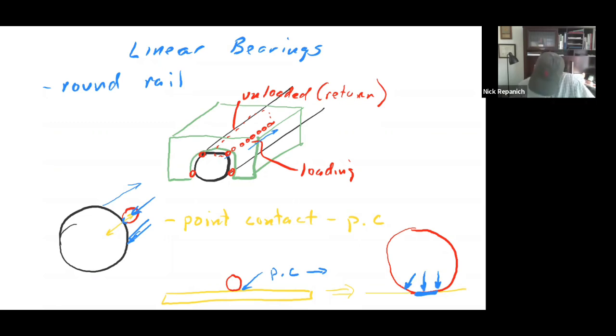Now, if you roll it this way, let's say instead of rolling it back and forth, let's say you roll it longitudinally into the paper, then you really start to see that the velocity here is different than the velocity here is different than the velocity here. And if you have varying velocities in a bearing, then you automatically have some parts that roll and some parts that slide. So the more you preload a bearing, I guess I'm getting into the weeds,